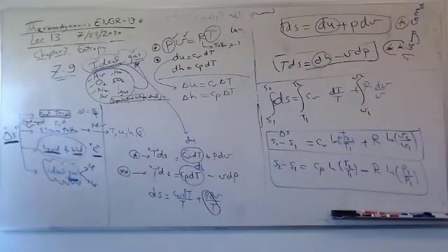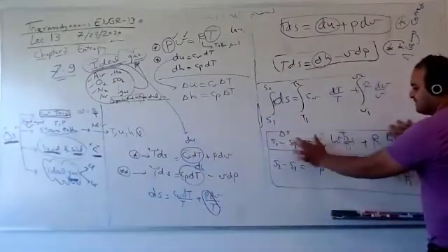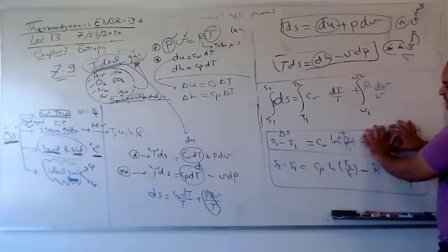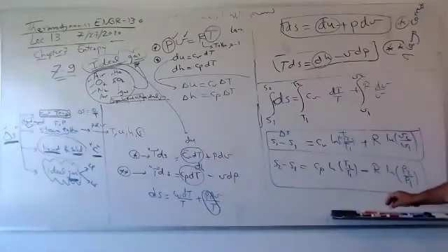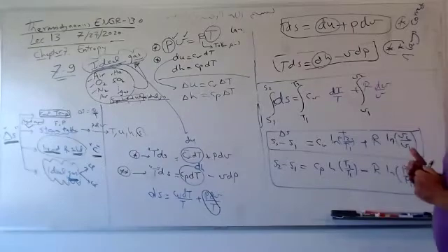So how can you get delta S for a constant temperature system from the steam table for liquid and solid? Liquid and solid is so easy. Actually, for liquid and solid, the volume is constant. It's just this special case. Now for ideal gas, we have V2 over V1, because ideal gases change their specific volume.